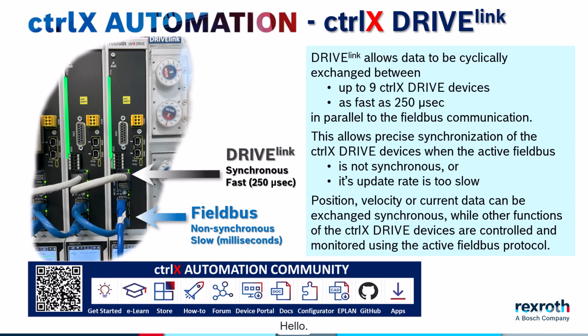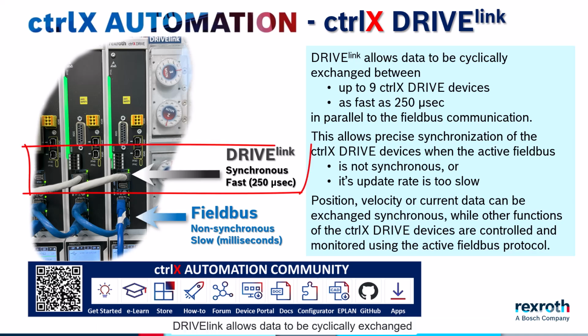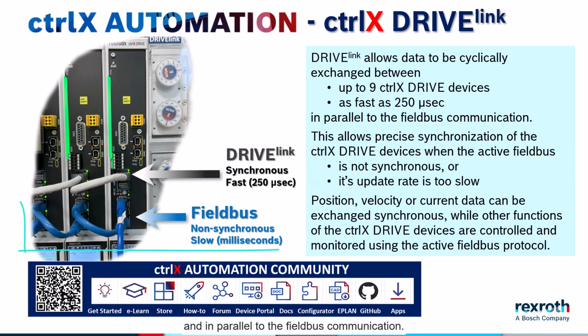Hello. In this video we explain the main benefits and functions of the ctrlX drive option, the DRIVElink communication. DRIVElink allows data to be cyclically exchanged between up to 9 ctrlX drive devices, as fast as 250 microseconds and in parallel to the fieldbus communication.